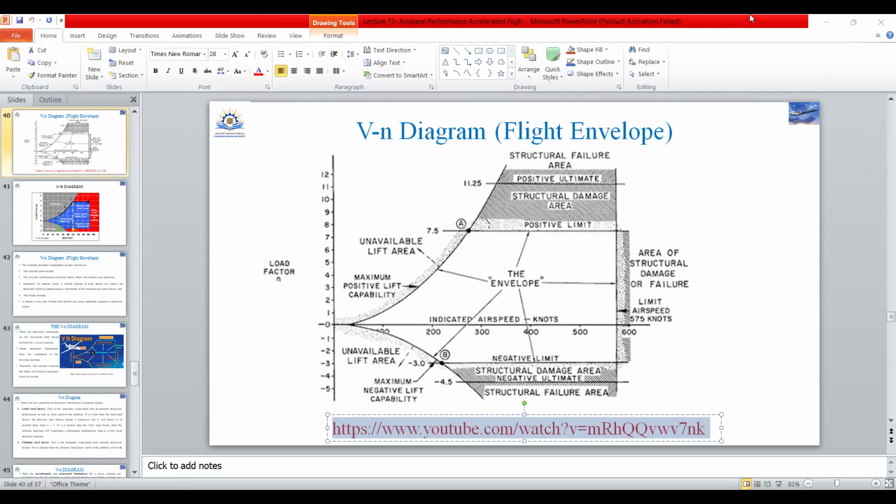If an aircraft is flying in this speed range, and if the positive load factor exceeds this value, there will be structural damage on the aircraft. If the load factor increases further, it will lead to complete structural failure. Beyond this negative limit load factor, there will be structural damage, and if the load factor drops further in the negative range, it will lead to complete structural failure.